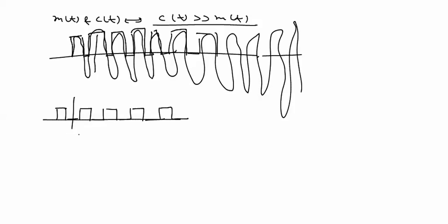We already know this carrier component has distinct frequency components via Fourier series expansion. A pulse train has all the basic frequency and its harmonics; the Fourier series represents its fundamental component and its harmonics.